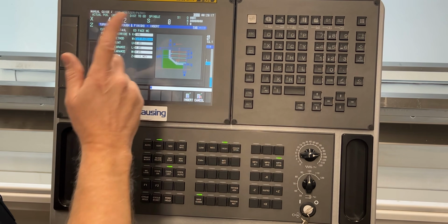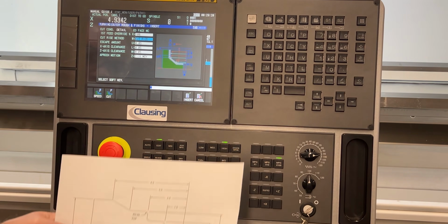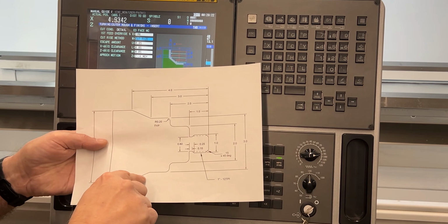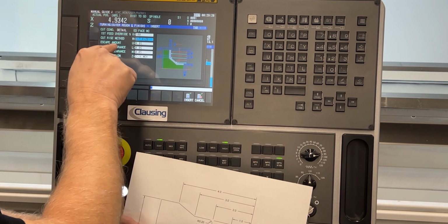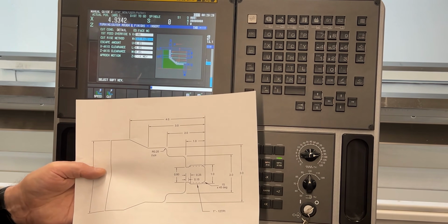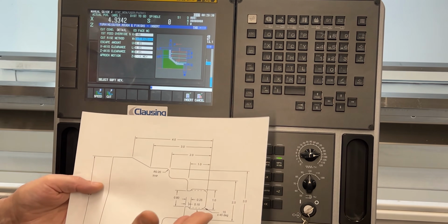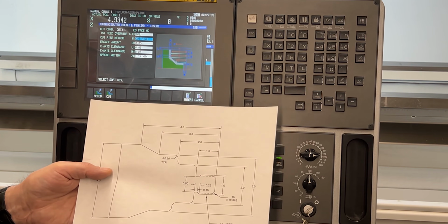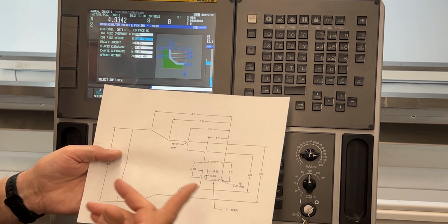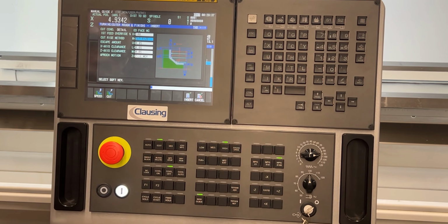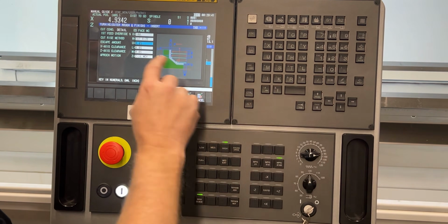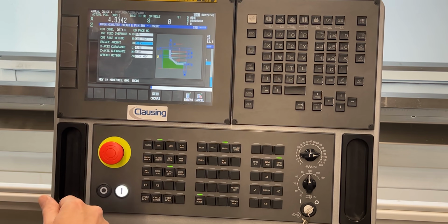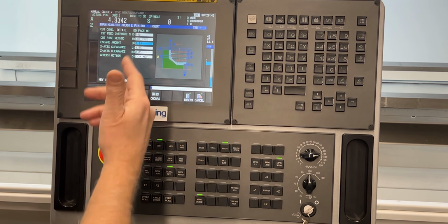The cut rise actually follows the contour. So when it's coming into an angle, it'll actually follow the contour out, by the amount in the escape amount, and then come back to the front. This blends in better. So when I do the finish, I'm not hitting basically what we'll call a stair step going down the angle. So I'm going to leave it with a cut rise, and then my escape amount, this is how much it backs off, and I'm going to leave that at 50.